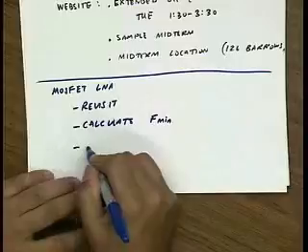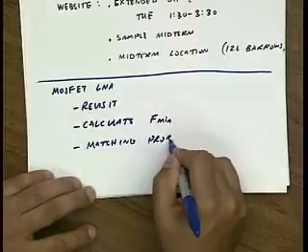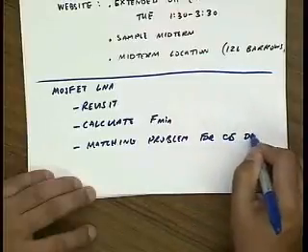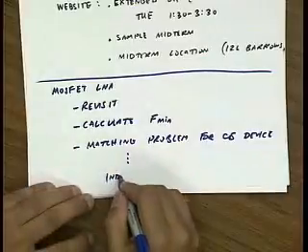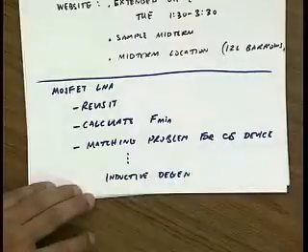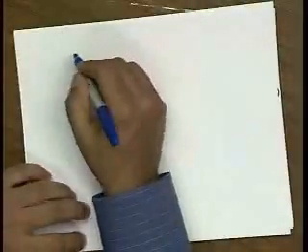And then we're also going to look at the matching problem for a common source device. And then the solution will be to use inductive degeneration. So we'll spend quite a bit of time talking about an inductively degenerated MOS amplifier. Okay? So let's recap the calculation of the noise figure.